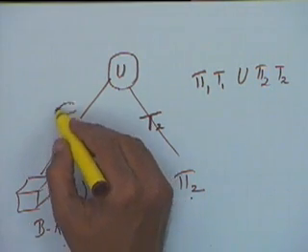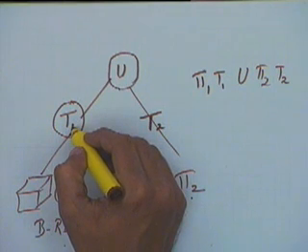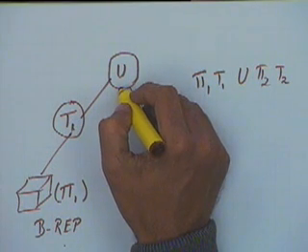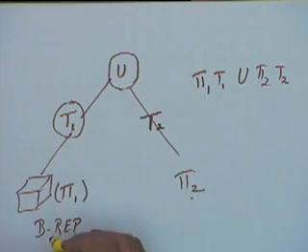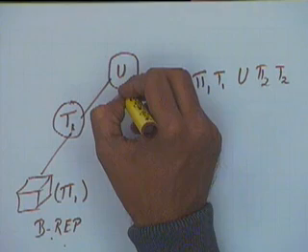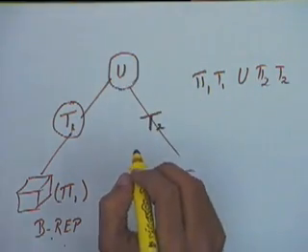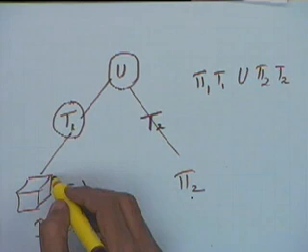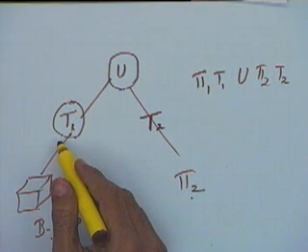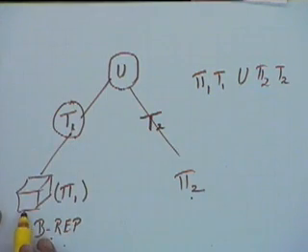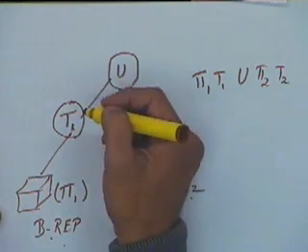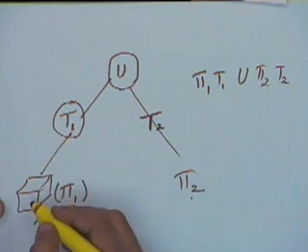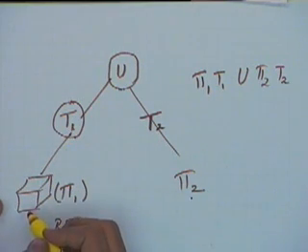So these transformations are normally relatively simple to use. It is only the Boolean operations which are expensive in terms of evaluation. If you are talking about a transformation that does not change the topology of the object, only the Boolean operation would do that. Transformations would change the properties of this solid. Properties meaning if I want to compute the volume of this object, a transformation can change the volume, because I can change this cube into maybe a block or a rod or anything. So the volume of this object can get altered. But the topology or the interaction between the surfaces, that will not get altered.